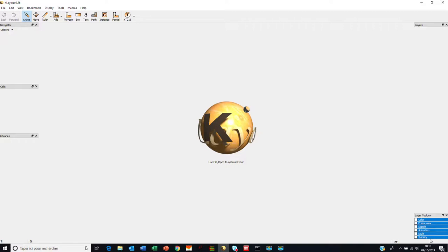This processing can be performed in the initial design tool or using a GDS2 editor such as KLayout, an open source tool that proved to be very handy for this. This demo will make use of KLayout. So the very first step is to install KLayout on your computer if you don't have it yet. The second step is to read the GDS2 file.